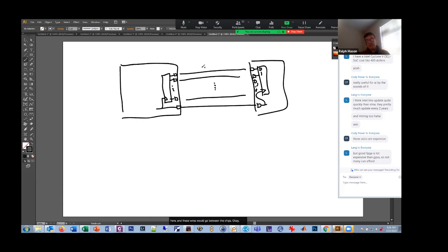Now, I might have a bus that's 32 bits wide, or I might have 64 bits. I don't know, bigger than that, it gets a lot of pins. But anyway, this was my clock, and all this stuff is data, right? Well, it turns out if I send a clock between these chips, going from one chip to another on a board, it kind of tops out at about 100 megahertz, okay?